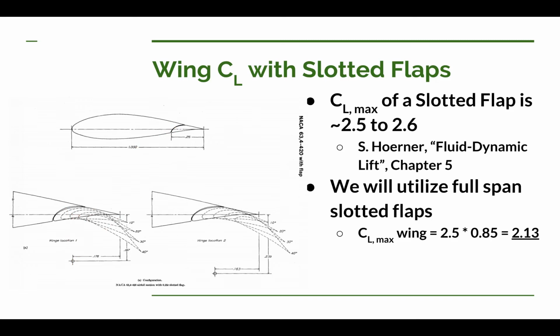An alternative is a slot mechanism, and you can have one slot or two slots. If you're doing two slots, you'd have one of those slots be to position the nose as you're sliding the flap back. The other slot would be to position the trailing edge of the flap as you're sliding it back. For something trying to represent a hinge, you could probably use one slot for both. But the difficulty with that is that that slot's going to end up hanging down here into the airstream. Even if you only want to try to manage a short slot, it's going to hang down a little bit.